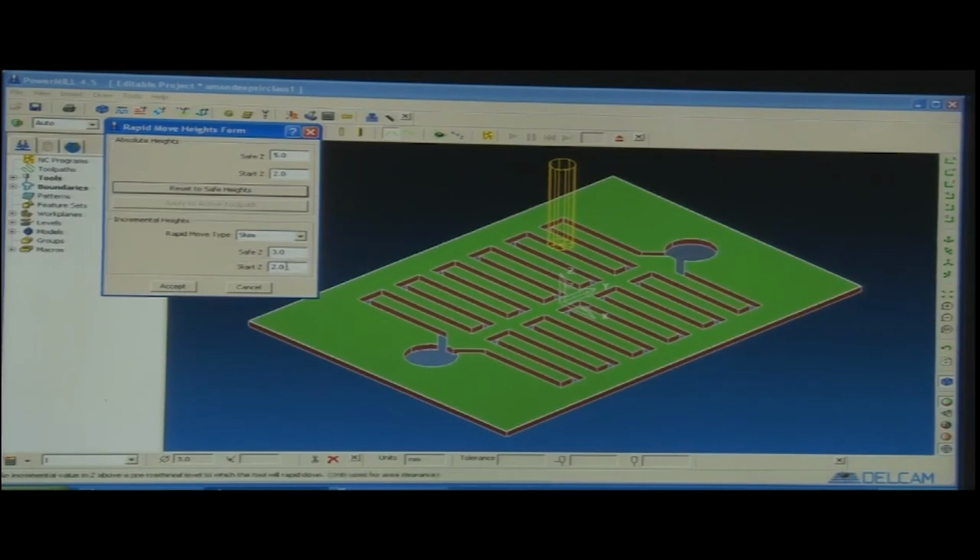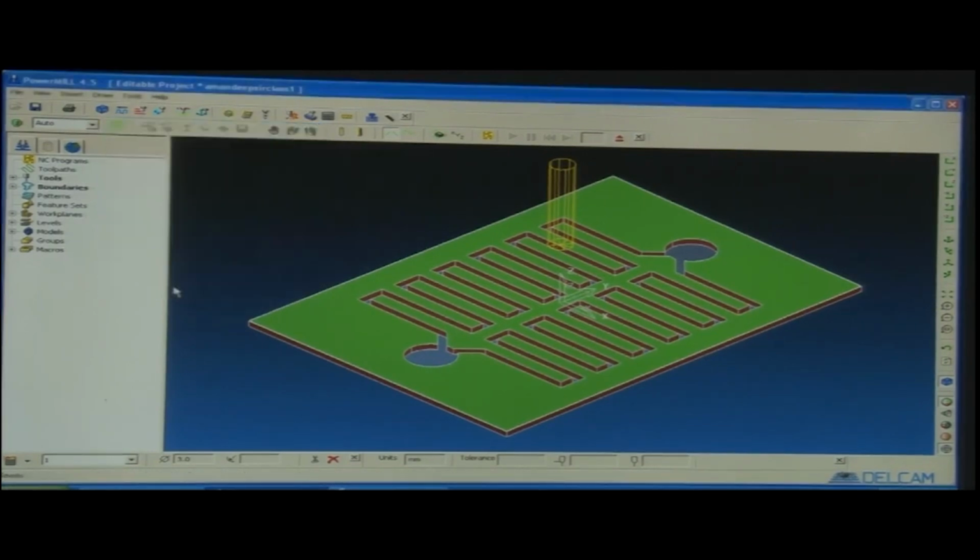It will then go down in 2 steps, 3 mm and 2 mm, when the actual cutting feed is given. So, this is a safe working height when the tool tries to enter the job from the top of the block. Sometimes the top surface is not flat or some roughness is there, like I just showed you with the mouse. If it has some surface, there has to be a safe height, and that is evaluated before we start the machining.